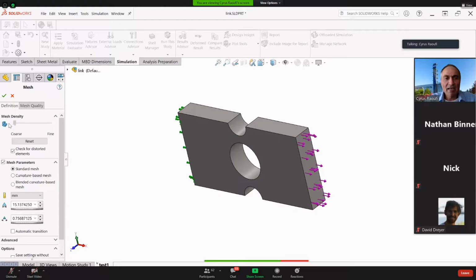You can move that one to the coarse, which is 15 millimeter size, and go to the fine, which in this case is 3. But it's not your limitation. You can go here and say I want to apply, I don't know, say fine is 2, more than that. Or I can go to coarse and say instead of this coarse limit, which is 15, I want to have 20. That is just a number. You have control over that number. You can play with that one roughly if you want to. You don't care about the numbers. All right, let's reset. When you go here, the default is the number that I mentioned. You can go to the coarse.